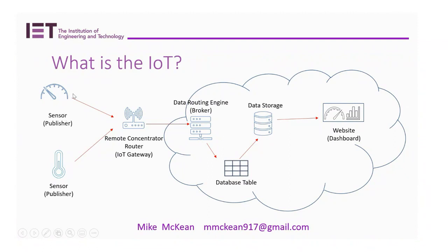So in an IoT world, the data comes in from the sensor to this concentrating device. And remember, I might be connecting here in a smart homes environment to 5 or up to 250 devices on one wired network, one wired M-bus. These devices are getting their power from here, but sending the data back to the concentrator. And let's say it's a block of flats. If I'm going to send the data back to this cloud, I need to identify that block of flats. So this will say I'm getting data in from these sensors, and the block of flats is reference 1234.